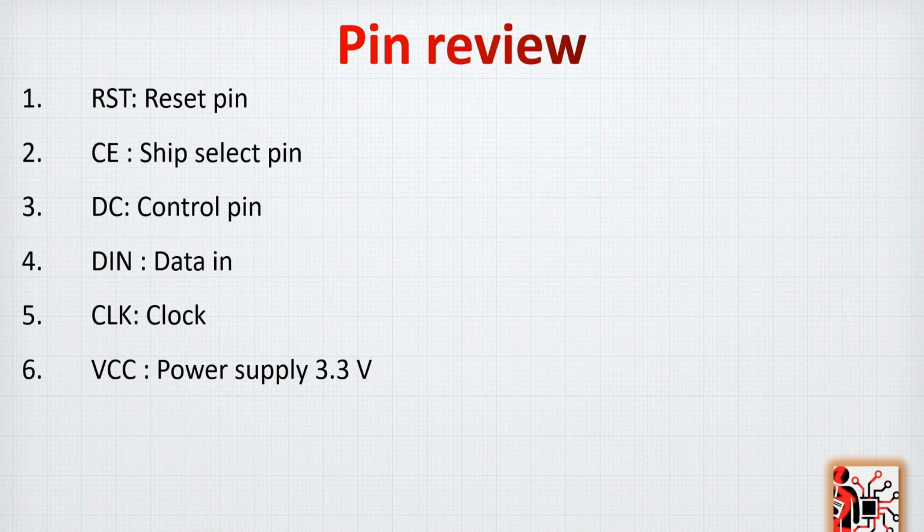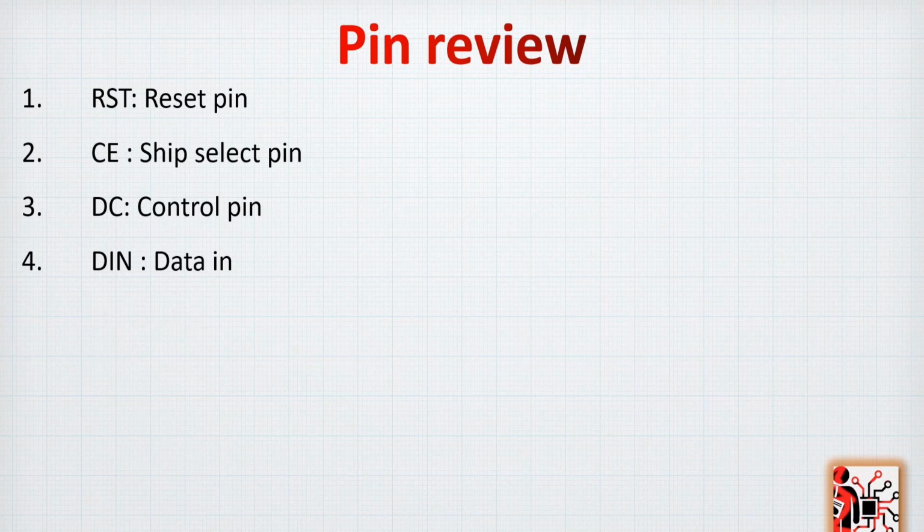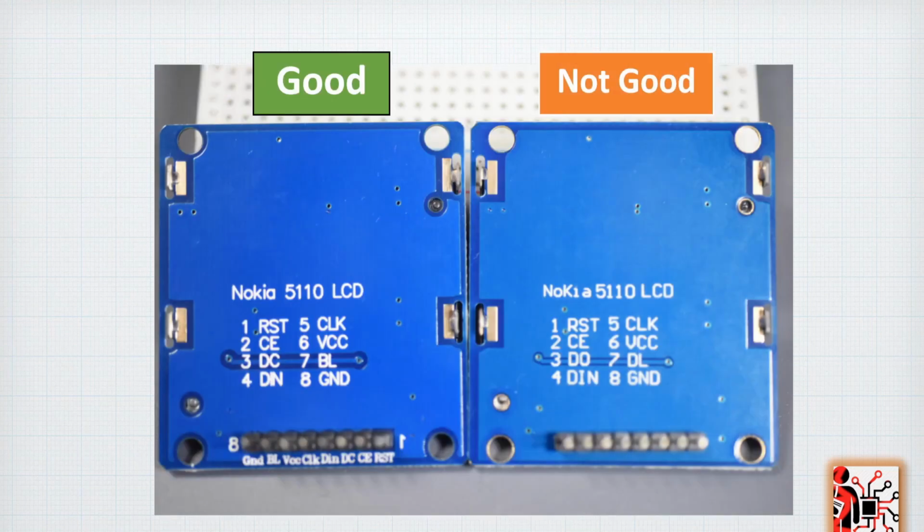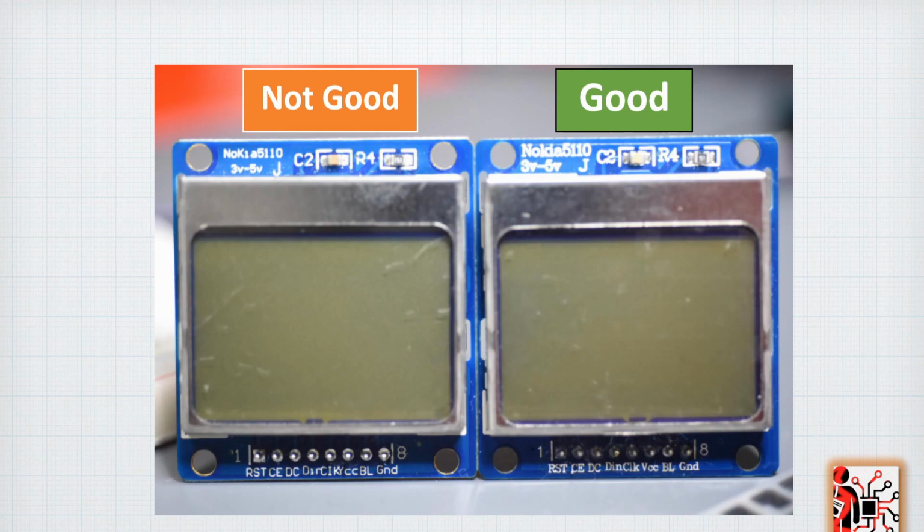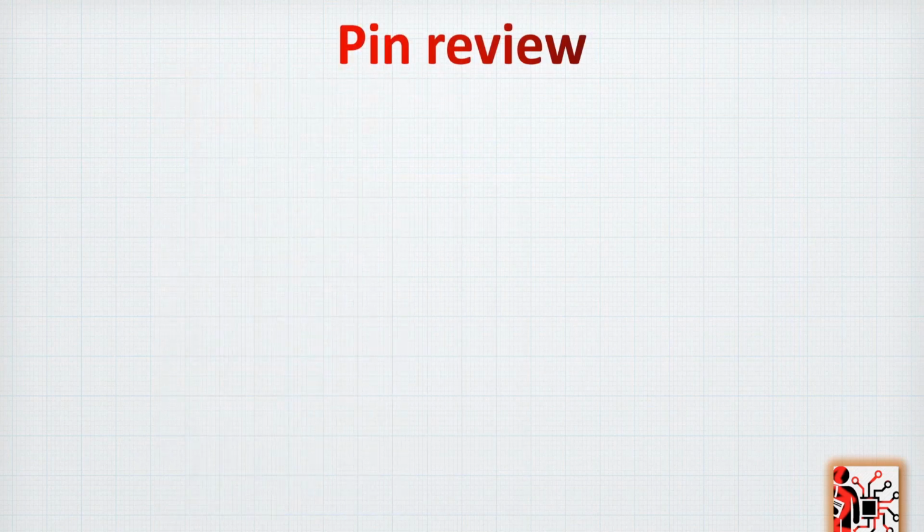The screen that I shared with you is also able to be supplied with 5 volts, but please try to connect with 3.3 volts, because 5 volts can destroy devices from other suppliers. This screen can be connected, as you can see, from 3 volts to 5 volts. That's good, but there's maybe a risk of having a problem with that.